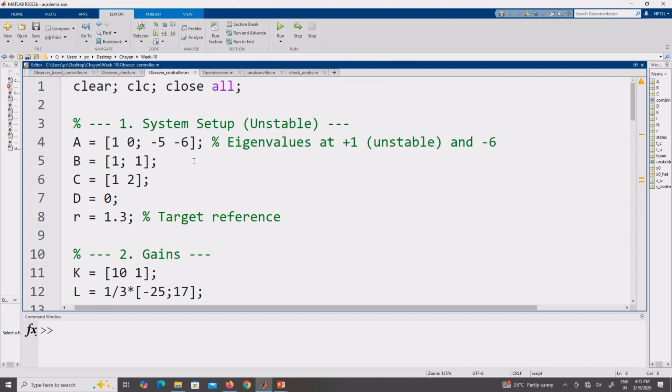Okay. So, this is the procedure to design both observer and controller together. Okay. Separately we are designing them. This is what the separation principle is all about. Okay. We design the controller using whatever methods that we have talked about earlier, and then we design the observer also. Only thing in observer is that we convert the problem into a controller design problem, and then we design the observer.